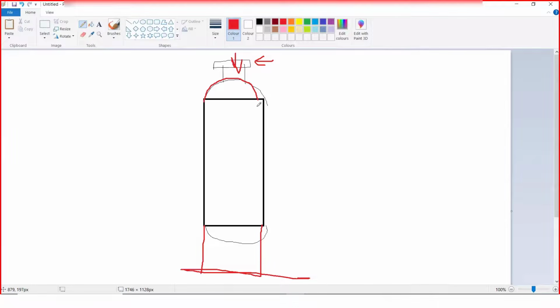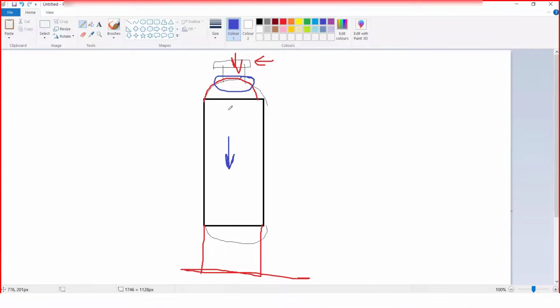So right now the software does what? The software performs the local load analysis at this junction caused by this nozzle and checks whether this junction is safe or not. But if this is acting in the downward direction, it is going to push the vessel down, correct? If it is going to push the vessel down, it will add the load at the foundation.